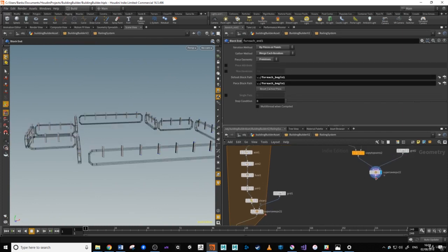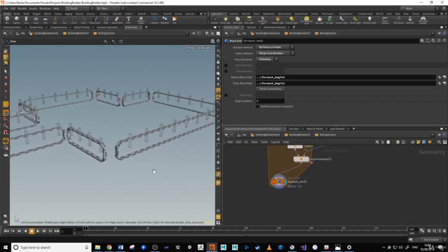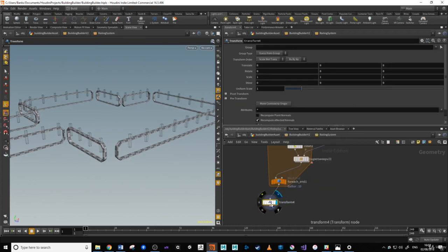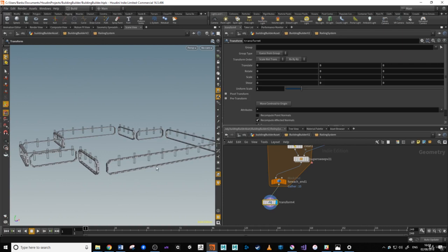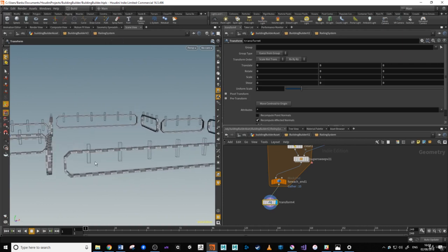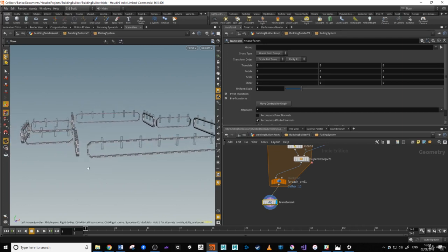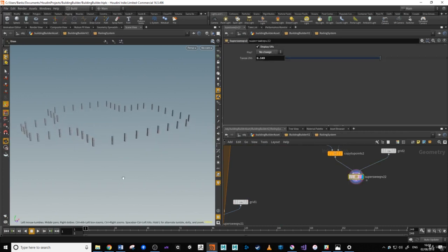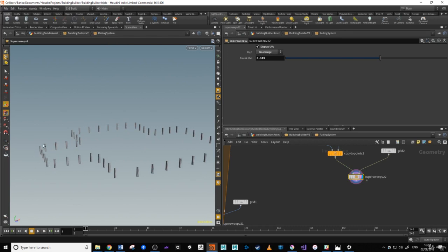So with that I'm going to template the uprights, and I'm going to come down here and work on this frame section. So we can put down a transform node on the frame section. And what we can do is we can reference the top of the frame using another expression, a Houdini expression, and that's the bounding box expression. All objects in Houdini have a bounding box which describes their extents x, y, and z.